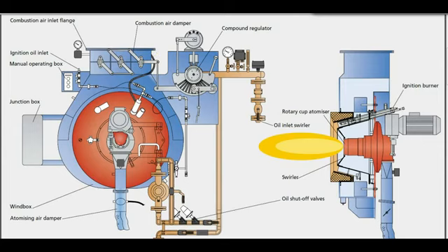And the burner rotates at a very high speed through a belt driven motor. So let's now understand how the oil is getting atomized. The fuel oil usually comes at 1 to 2 bar, depending upon the boiler design and the ship's boiler fuel oil system. So I'm just giving a rough example of 2 bar.